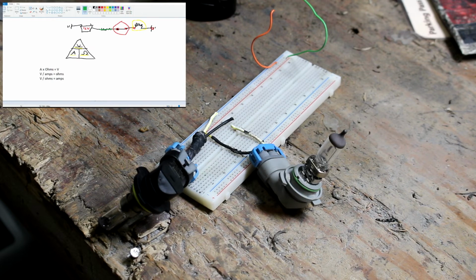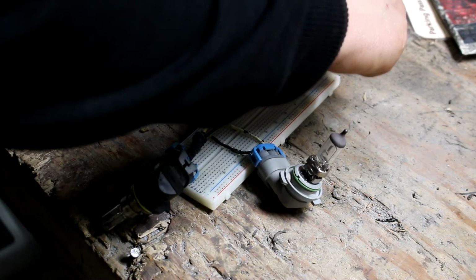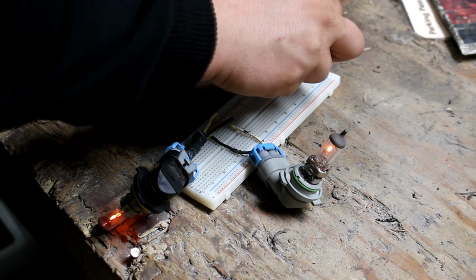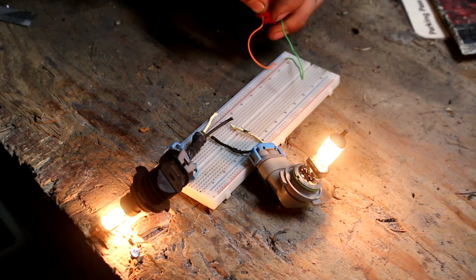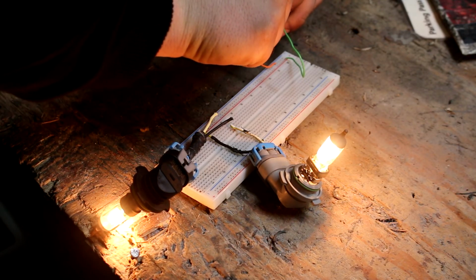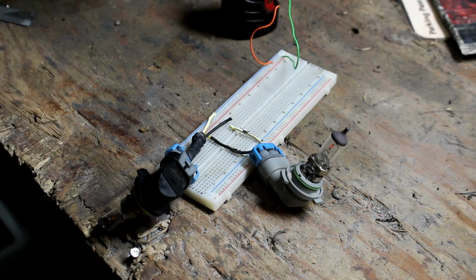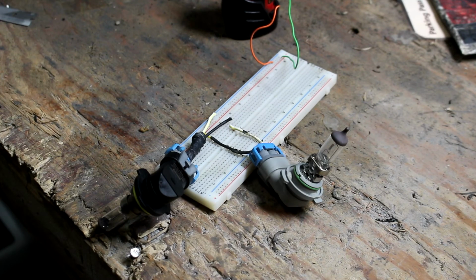So remember how bright that bulb was before? You just saw it. Here, I'm going to put a screenshot of it right now. That's it before. This is it after with that green wire in there. A little bit dimmer, huh? The reason for that is because of that green wire. Now we're going to get into our second law of the evening. The second law is Watt's law, and Watt's law is volts times amps equals watts.